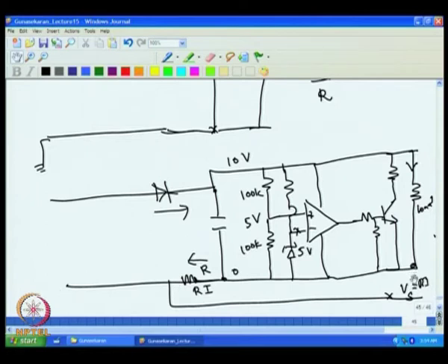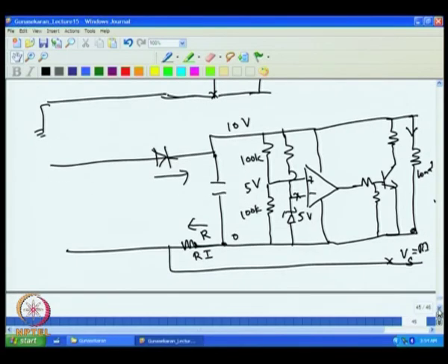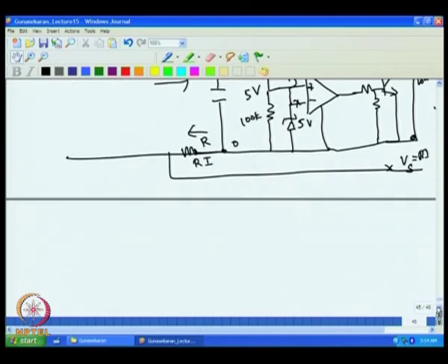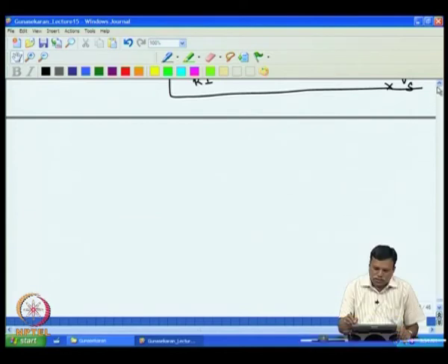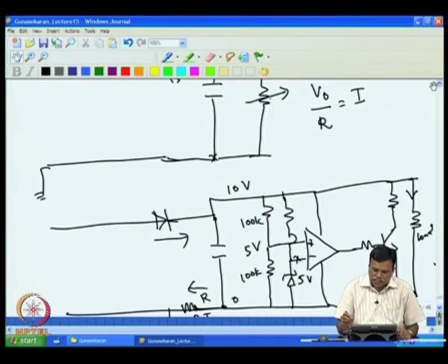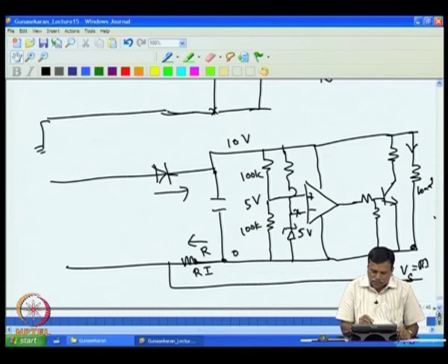So, we have now used this regulated power supply voltage and this signal to activate some process. The first step would be to convert this signal voltage into a usable positive voltage, because if you look carefully, the voltage across this is negative, because this is our ground point and current is flowing like this. As current increases, you will have more and more negative voltage here.